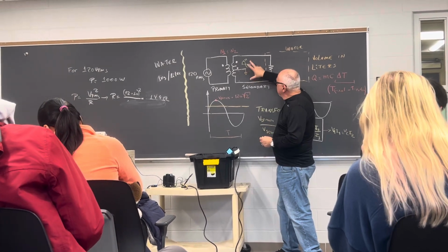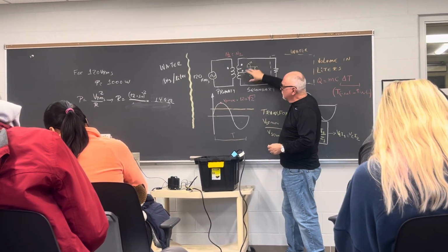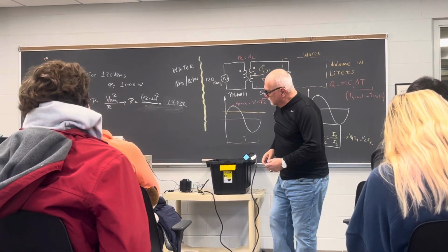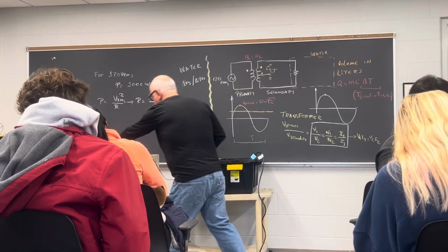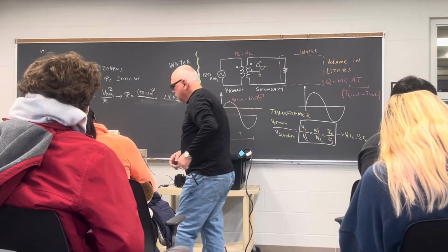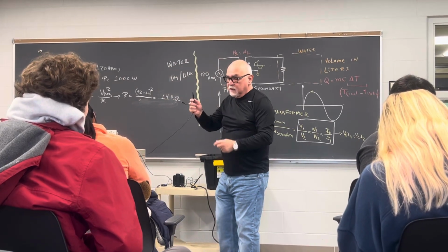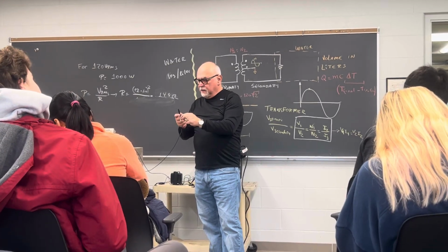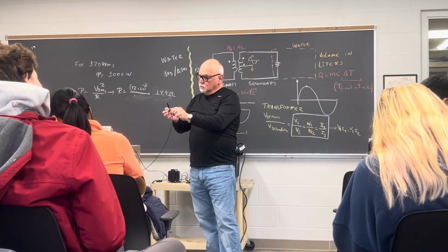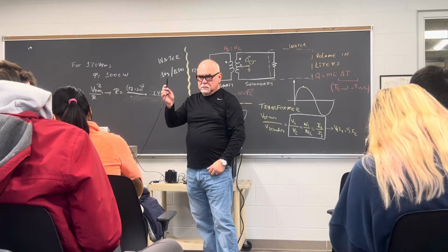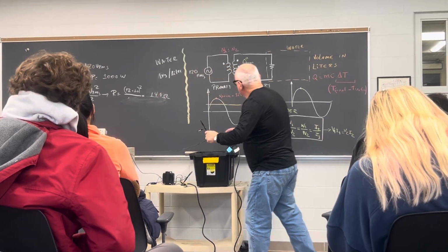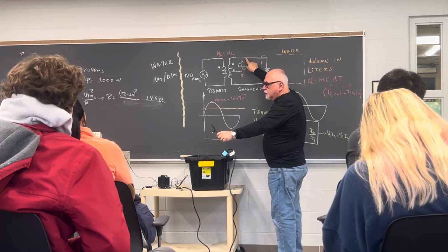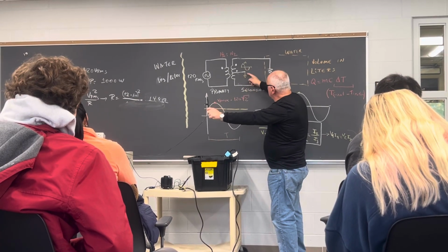But now I'm going to measure both, okay? Because we're measuring from here to here. I'm going to measure both, but initially, I will do this. You have to be careful, I told you, with your ground, particularly when you work with things like this that are a little higher voltage. So do not use this ground without thinking about what you're doing. I have a probe from center tap to here. Now I'm going to measure the other side with this probe.